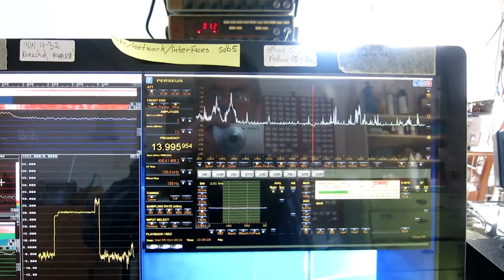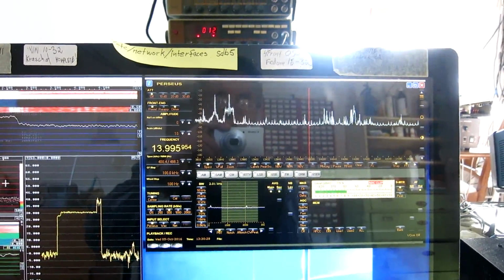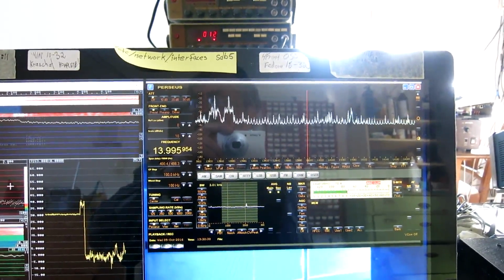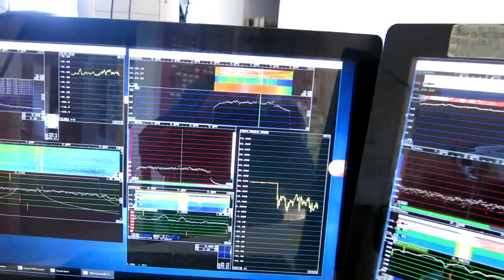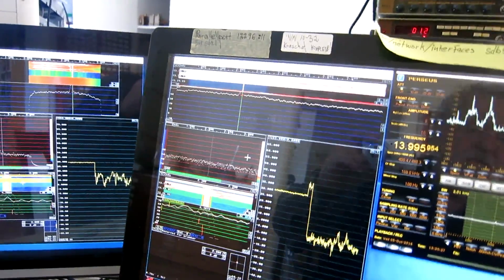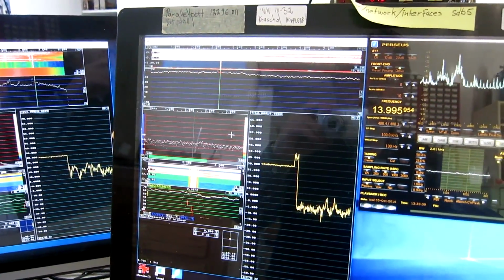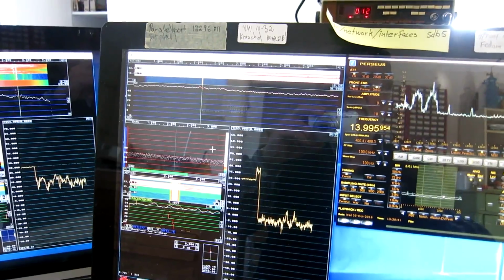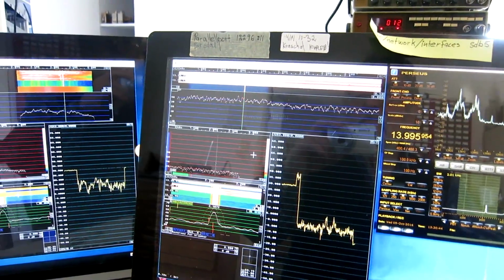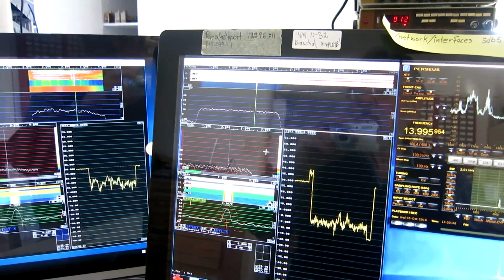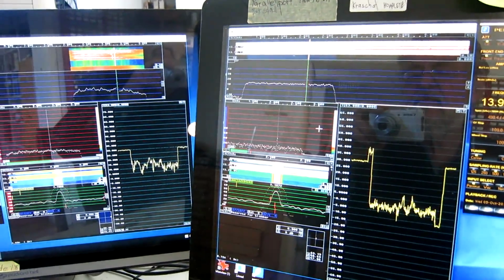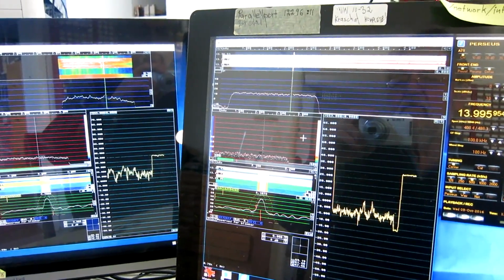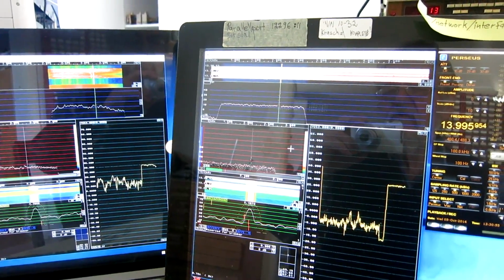I now connected the 14 megahertz dipole, and it gives more signal, as you can see here. Both radios are severely saturated. So I bring in some attenuation, 10 dB. That was more than enough. So I bring up signal levels. 1, 2, 4, 5.